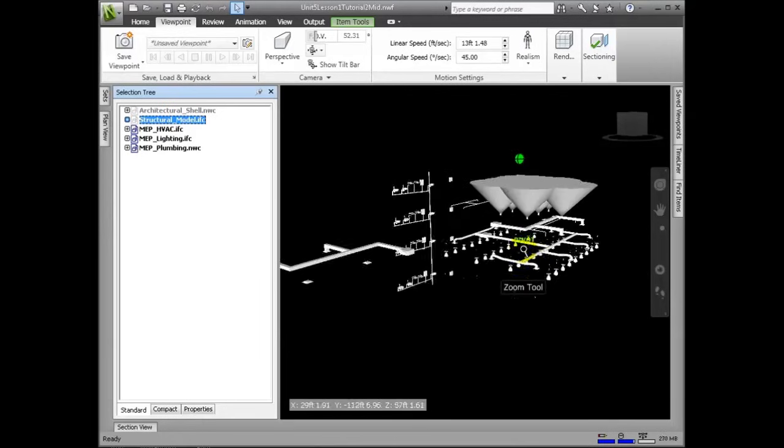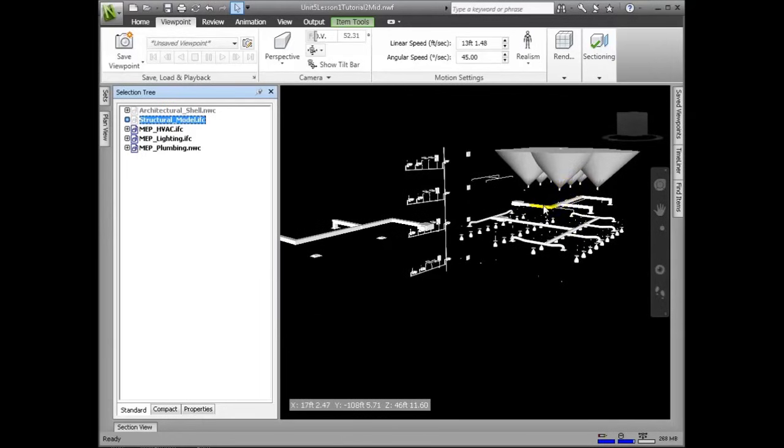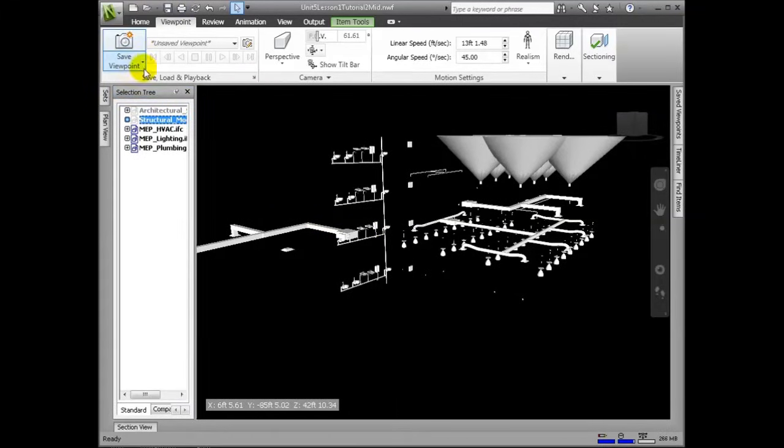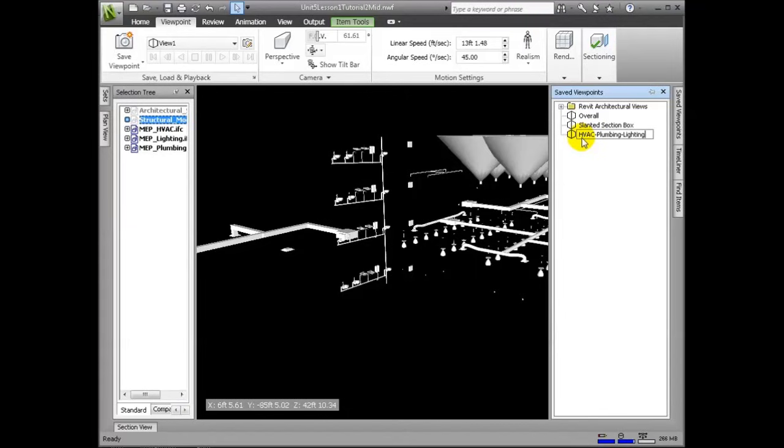Let's go ahead and create and save viewpoints of interest by combining different camera angles, cutting sections, and/or hiding or requiring elements or whole categories of elements. Let's make some viewpoints that isolate out one or a couple of disciplines, and we can also arrange them into meaningful folders.